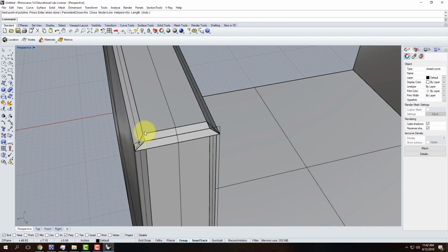If you go out and you look at the corner on the concrete, you'll see that they have to manipulate the corner. Now, typically, we don't build formwork for that corner. We would just, when we take the formwork off, knock the corner off, so it's not quite so sharp in the corner. But it's the same problem. You have to figure out how to meet these pieces together. So now that I have that, I can trim off the extra pieces. But I want to point something else out before I actually do the trimming.